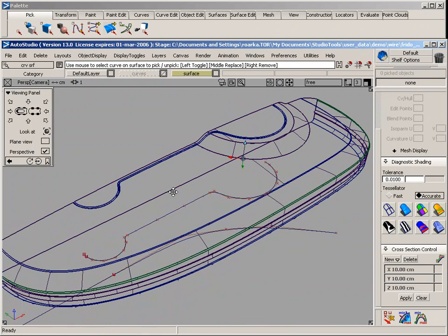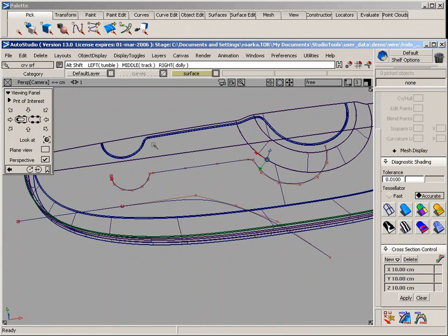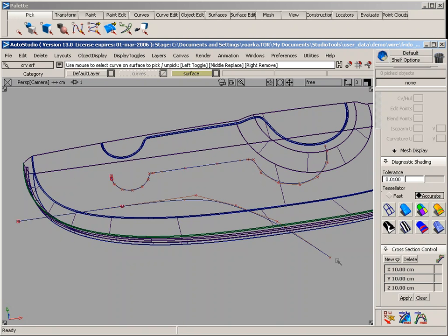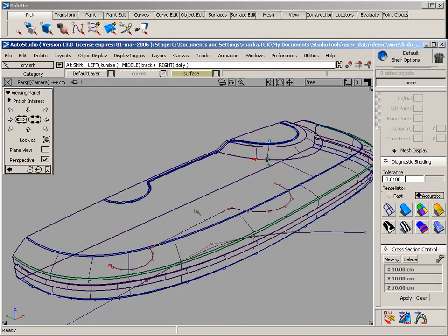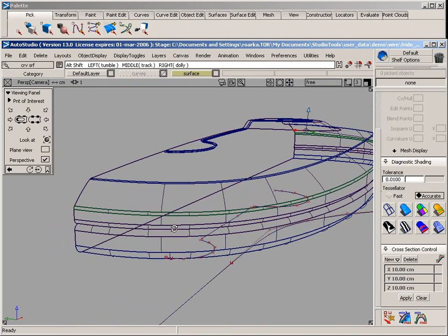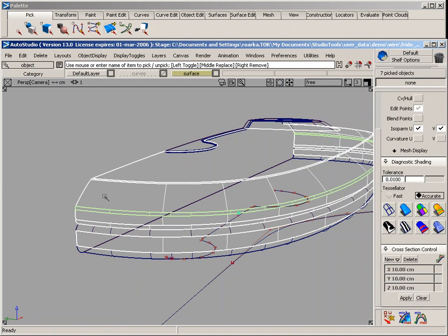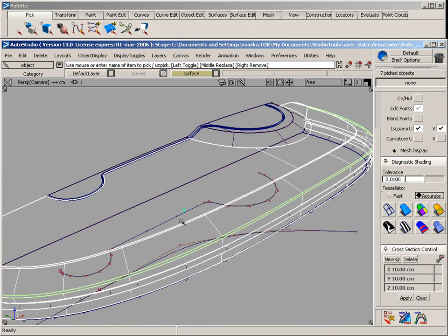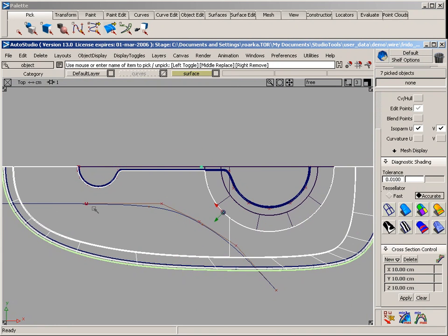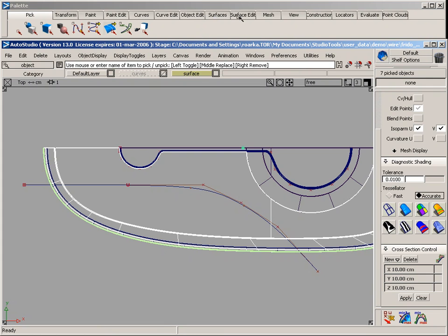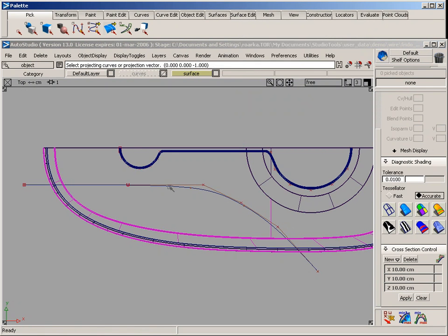So with this now in place, what I could do is add some more revolved shapes here, keep on trim dividing. However, for this part, all I'm going to do is project this curve that I earlier did in the top view onto my surfaces and do one more trim divide and assign some different colors for the diagnostic shading so you can see a little bit what this will look like. So for that, I'm going to choose all of these surfaces in the top view, F5, use this one to project it onto it. Create curves on surface, project, choose this one,